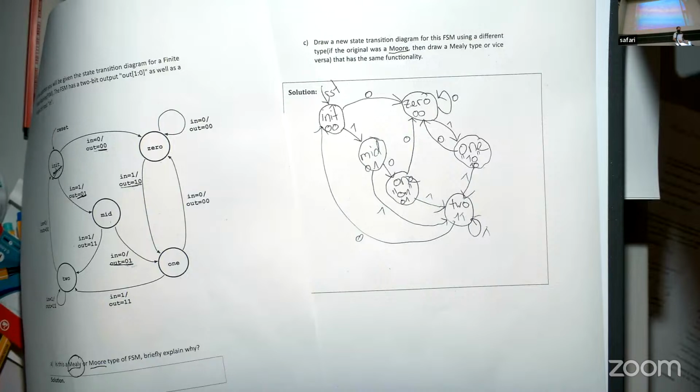Another question. For the Mealy machine, you have to define what happens with the output on reset, because in the left diagram, it is not specified what the output is after reset, before any other transition. That's true, but by definition, a Moore type FSM has an output in the reset state, in the init state or whatever, right? It has an output in every state. In that sense, I guess they're not 100% equivalent.